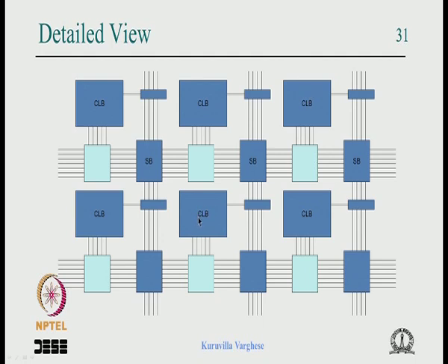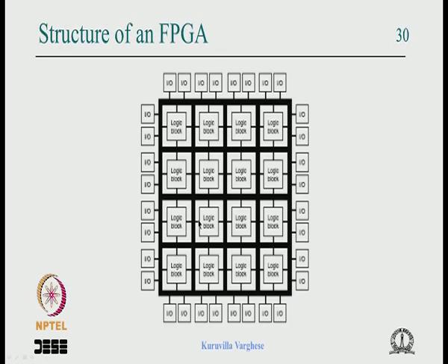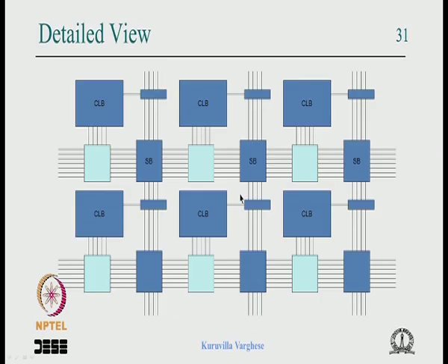Okay, that is one thing once again you should remember, not only are the wires programmable or configurable, the logic within the logic block is also configurable. So there is not only programmability in terms of interconnection, there is programmability within the logic block, okay, to make it very flexible. So when you say configure FPGA, it means configuring all these connections as well as configuring the logic block, okay, that should be kept in mind.